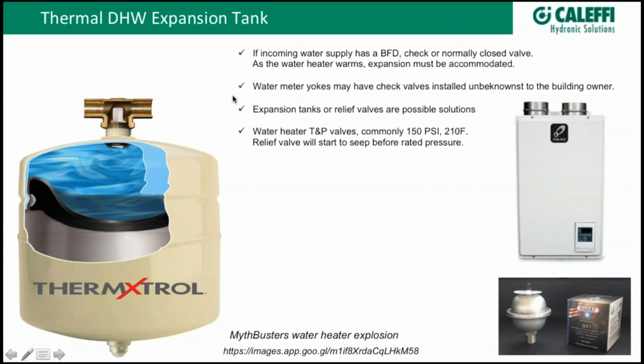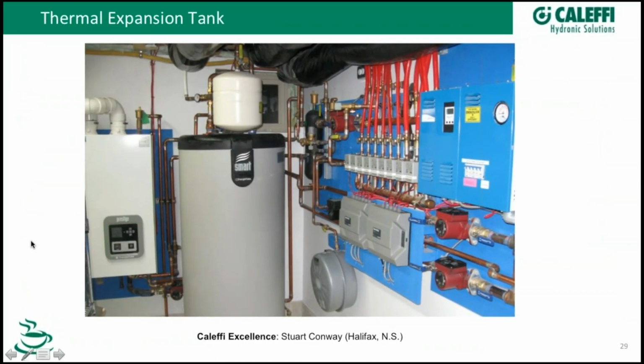One thing I noticed where I was working years ago in Park City, Utah, is we started getting calls all of a sudden out of the blue that people's water heater valves were starting to drip. Maybe there's a bad batch of relief valves out there. What had been happening is the water department was going around and replacing the meter yokes out on the street. We had meter pits there, and they were putting in meter yokes with backflow preventers built into them to protect their potable water system. And they weren't telling the homeowners, or at least the homeowners weren't aware, that they had to put an expansion tank on to prevent that relief valve from popping.